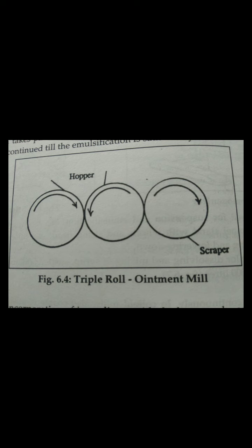Then, the roll on the extreme right with the highest speed takes the ointment off the slower moving roller and the scraper collects it. Okay, there is a provision of cooling the rollers by water jacketing them to prevent an undue rise in temperature due to friction.